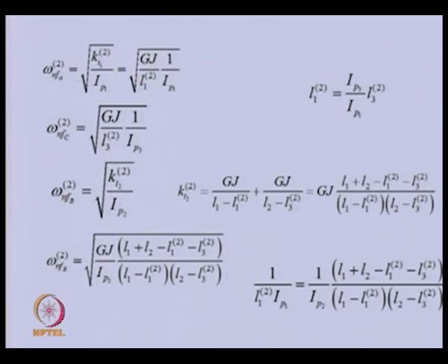So, this is the natural frequency expression for the left hand side cantilever, single disc rotor system. This is for the extreme right side corresponding to the disc 3. So, IP3, and you can see this particular length is the shaft segment for that particular cantilever in the right side.